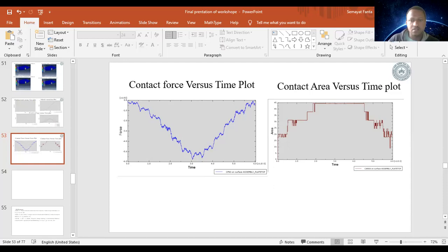General, here the file. So now it is ready to run. The job UMAT is ready to run, but I have no Fortran compiler on my computer, so it will not run on this computer.